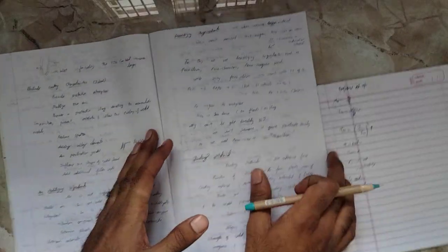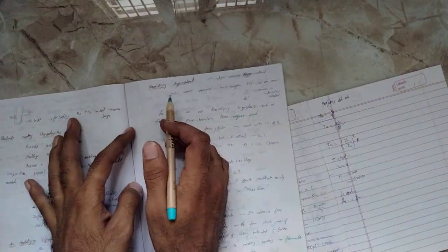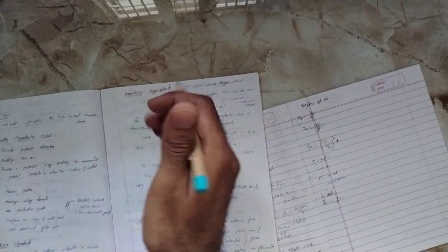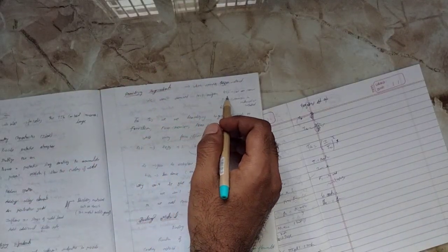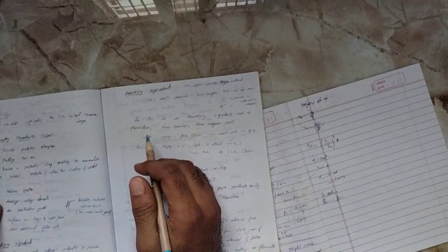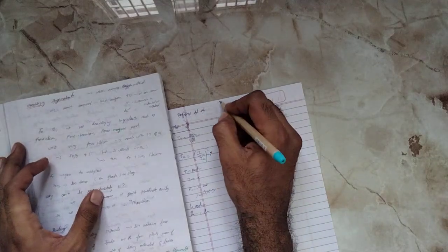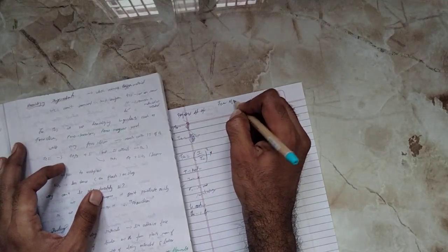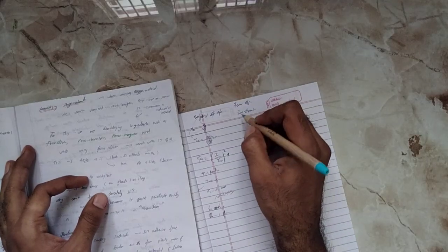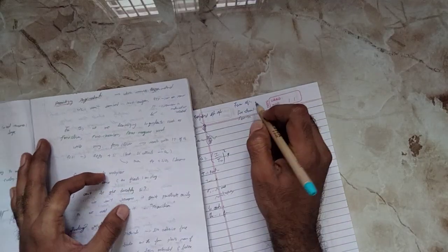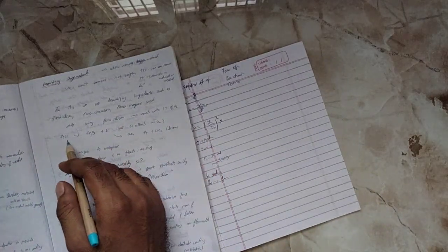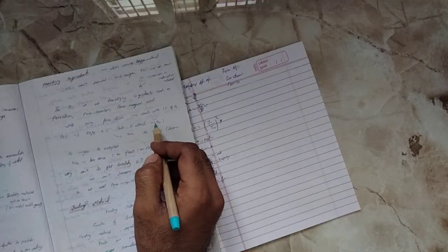Okay, next thing you can just see about the deoxidizing ingredient. Sometimes oxygen also gets infiltrated into the material, so we can't remove 100% of oxygen. We can remove about 99%, but 1% will still remain inside. For that purpose we will use ferrosilicon, ferrochromium, magnesium. While using ferrosilicon, it reacts with the 1% of oxygen.